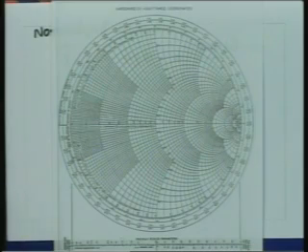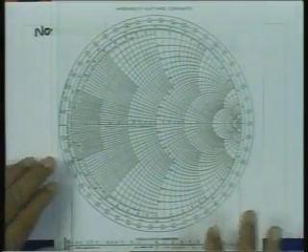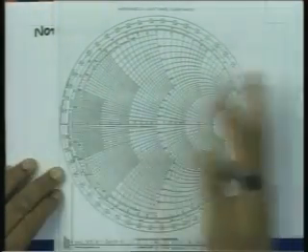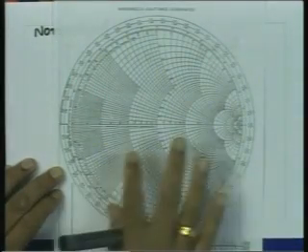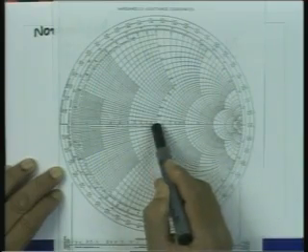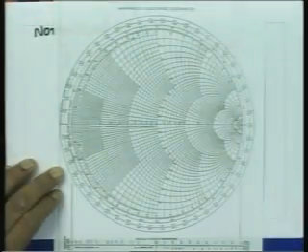So, if I develop an understanding that I will not rotate the Smith chart and will always use it in this form, that means the most clustered portion of the Smith chart is on my right. Then if I do the impedance calculations, the positive real axis is towards right and the positive imaginary axis is upwards.